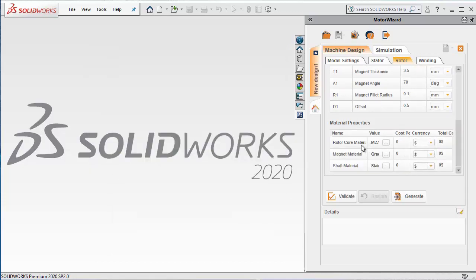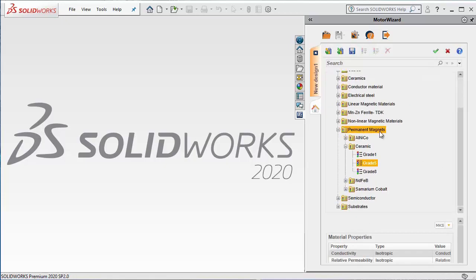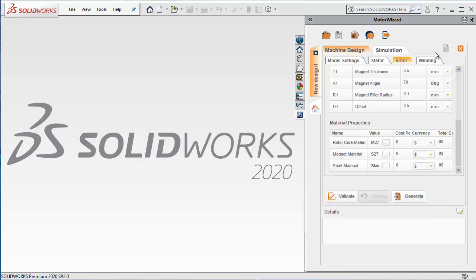I will keep the rotor core material as M27 with core loss, which was defined by default, and also the shaft material, which is stainless steel. I will change, however, the magnet materials. So I will click on Browse Material. Under the Permanent Magnets Material folder, I will select the samarium cobalt and choose the first magnet material. Then I will select Apply Material.